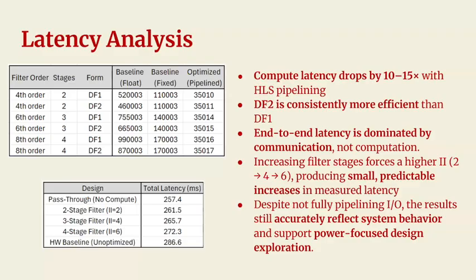During implementation, we found that using an aggressive pipelining schedule caused bitstream generation to fail, so we had to relax the initiation interval for larger designs. This naturally introduces a small predictable increase in compute latency. So the main takeaway from these results is that in this system, communication overhead dominates the total latency. That's simply the reality of this particular platform and data movement pattern.